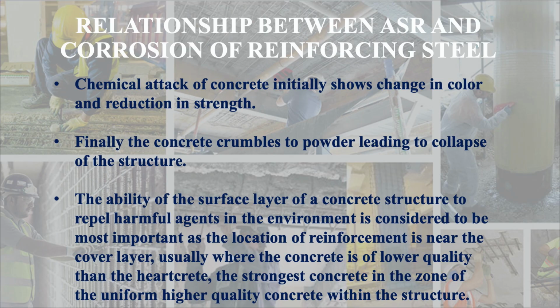The ability of the surface layer of a concrete structure to repel harmful agents in the environment is considered to be the most important, as the location of reinforcement is near the cover layer, usually where the concrete is of lower quality than the zone of uniform, higher quality concrete within the structure.